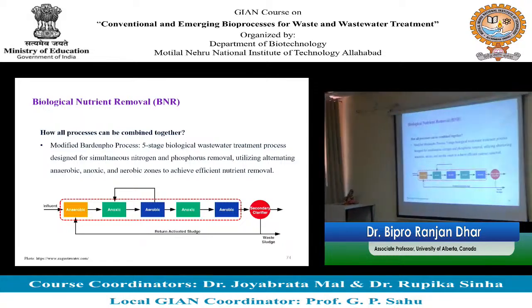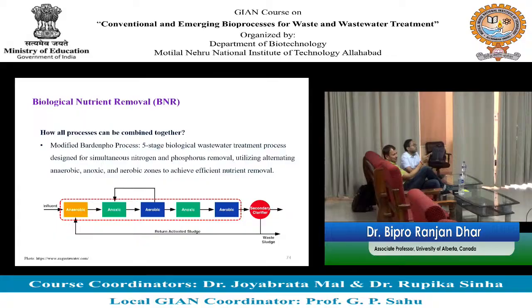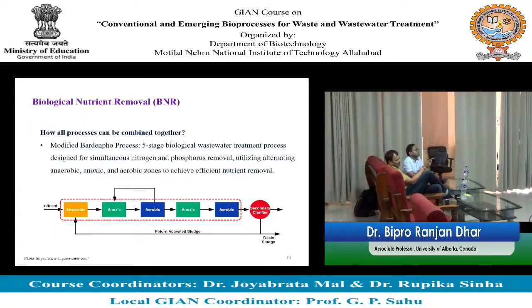No, but here we have the aerobic microbes. Yes, aerobic microbes. But why are we circulating those microbes to the anaerobic tank? No, that is what he is saying, it's not a separate tank. It's the same tank with different zones. Again, you have to maintain a certain SRT for this, and a certain biomass concentration in there as well.